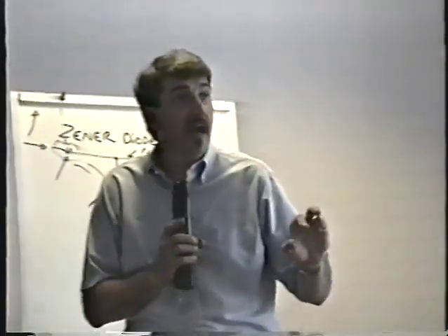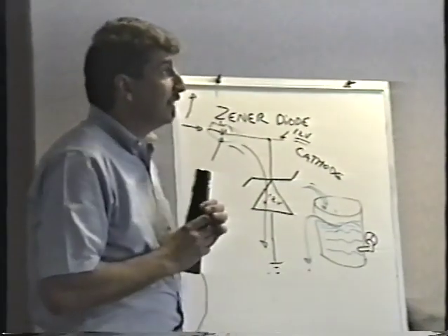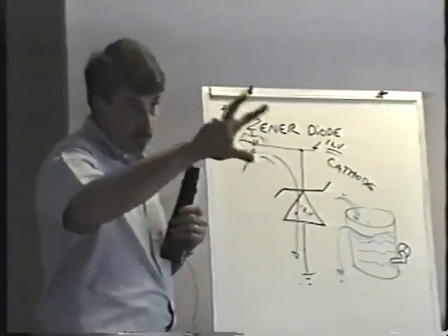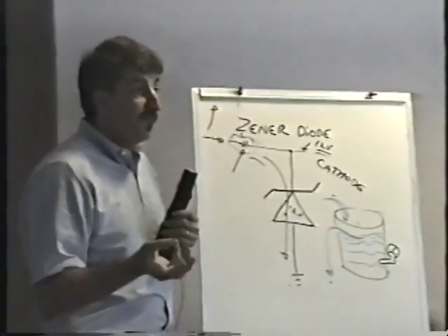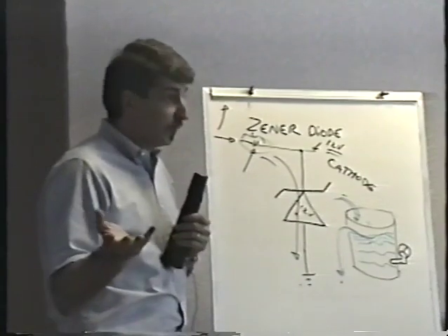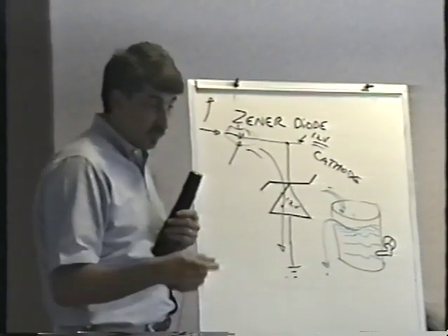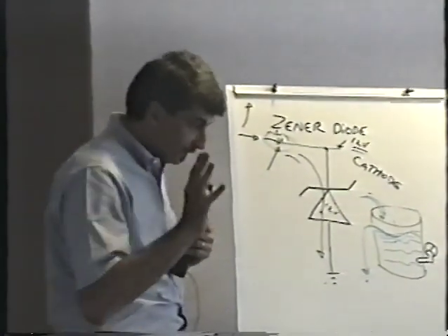It looks like a regular diode too. If you don't have one in front of you, it looks like a regular diode. There's nothing unusual about the way it looks. When you have a good Zener, it will check like a normal diode, open one way and a junction drop the other. When it fails, it will probably short circuit just like a regular diode does. However, there's a however for you.